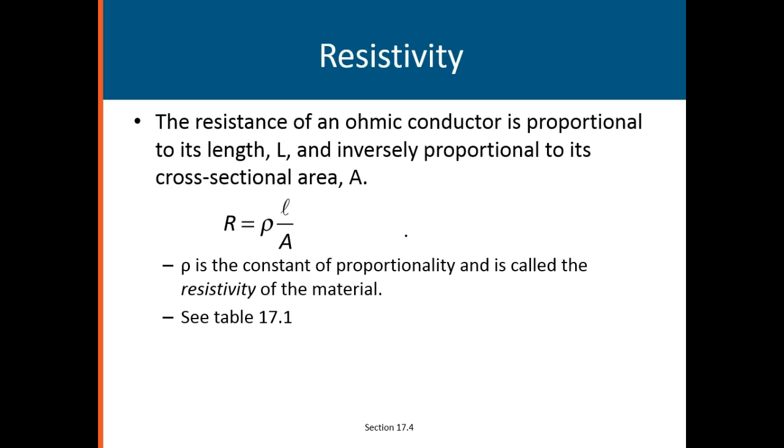You've all touched nichrome, I bet. You know the heating elements in your electric range, the thing that turns red when you turn it on, or the oven, if you have an electric oven, that thing that goes around there that turns red when you turn it on, nichrome. Heating element. If you ever have a space heater, the space heater has those little coils that turn red when you turn it on, most of the time that's nichrome. Very large resistivity, meaning it's resisting the current, which produces a lot of heat.